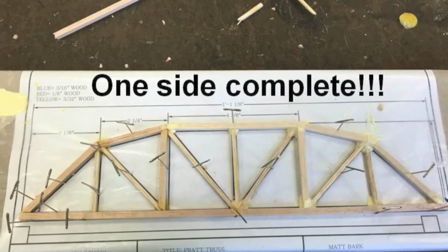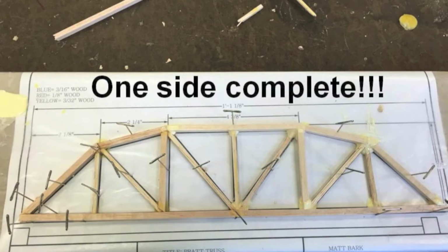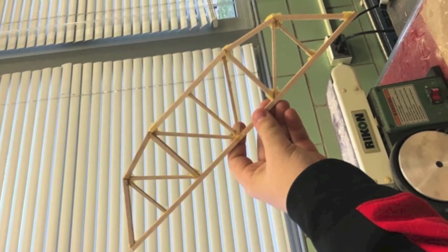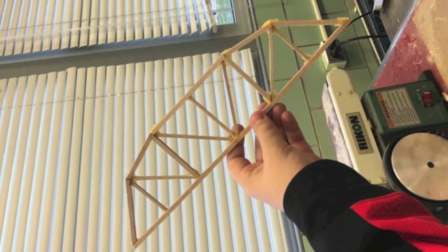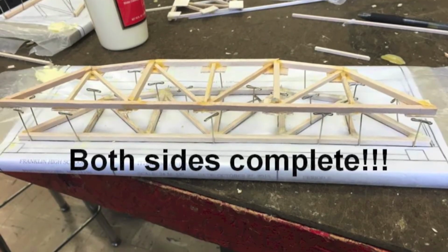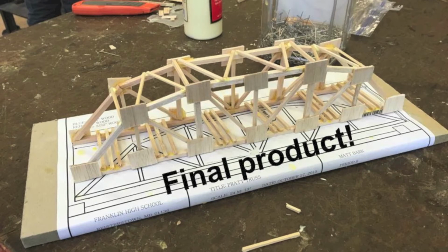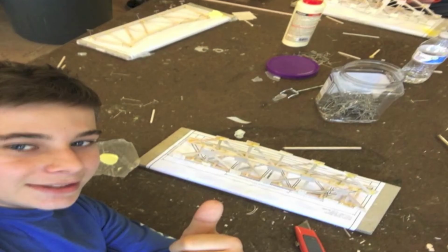I printed the blueprint and began building the first side over the blueprint with wax paper. After the first side was completed, I applied gussets at all of the points to strengthen the joints. I then had to repeat the process with the second side. I did the exact same thing, and then had to connect the two sides. I cut 30 1/8 inch pieces of wood spanning 2 1/4 inch long to connect the bridge. Then I began the testing process.